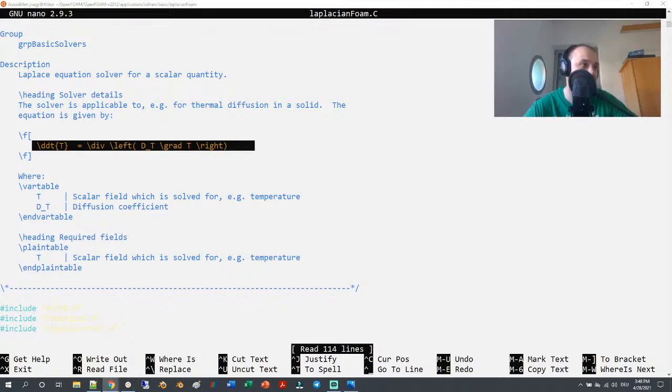What do you think about decomposition for snappyHexMesh? Good idea. So I guess the question is whether to run it in parallel. Yes, so I use hierarchical, that works well, and I run it in parallel, and I use reconstructParMesh to bring them together. I just finished a project with 40 million cells. There I had to use decomposePar, and it took me 30 minutes to generate 40 million cells on 16 cores. So it is great, it works well. So I like decomposition for snappyHexMesh, for big meshes.